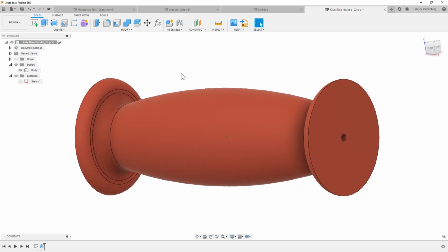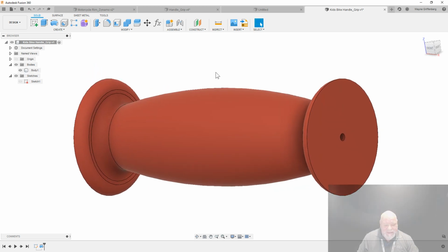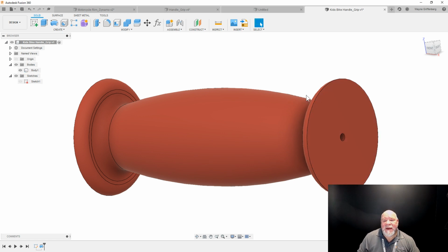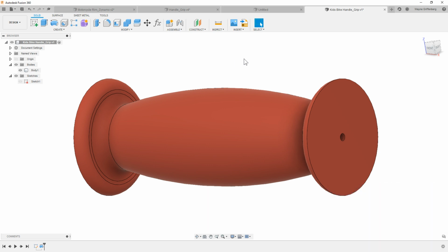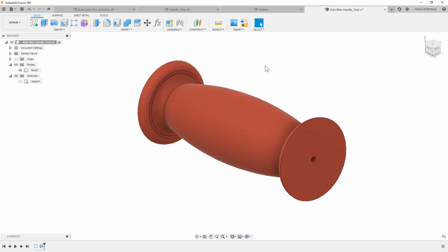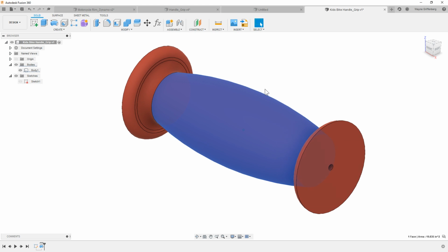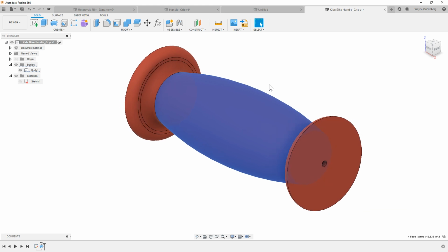And you think about how you would design that in a CAD tool. You'd make a plane in here, and you would make a sweep angle, and you kind of make a little circle and a sphere, and then follow that sweep and then pattern it. It can get pretty ugly. So a way that we can do this is I want to export this surface, right? So you can bring T-splines, you can bring surfaces, different bodies into Dynamo and manipulate them.